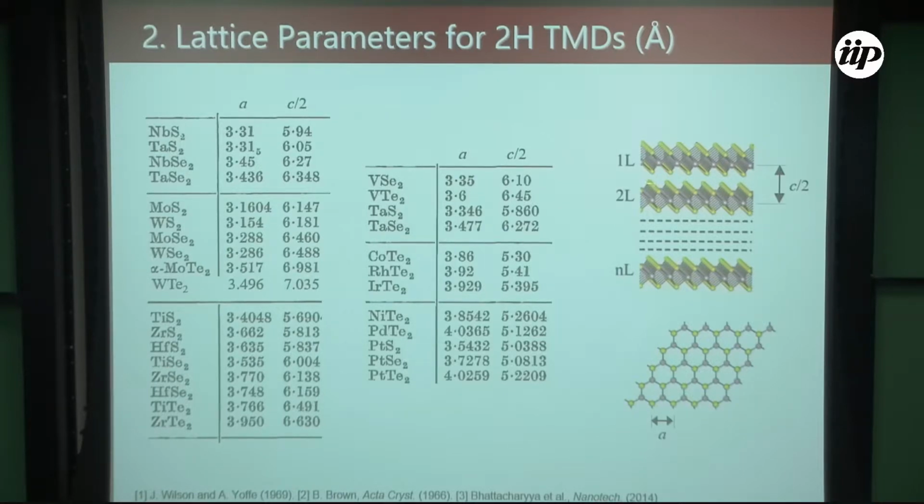And here's where things really become important, because if you're trying to compare the thermal conductivity of a monolayer, bilayer, or bulk, you better get the thickness of bulk when you multiply by n layers. And that's why that actual monolayer thickness, you have to get it right. Otherwise, you're not going to be comparing the right thickness, right? Electrically, for mobility, it doesn't matter, right? But for thermal comparison, it matters. And we need to be consistent with graphene and graphite, which we have been; the graphene literature is fine.